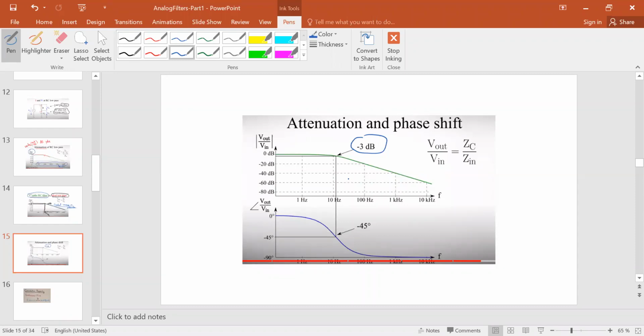Whereas in reality, when we design a filter, the filter will have some magnitude plot, and at the same time, it will have a phase plot. So in other words, when we design, it will not only change the magnitude according to our specification, so it has a slope, but it will also change the phase of the frequency component.